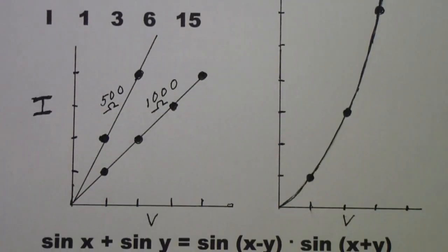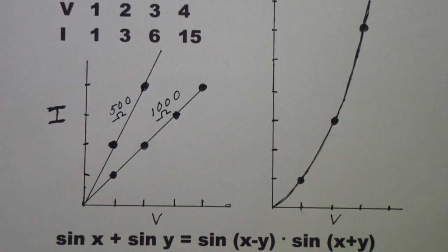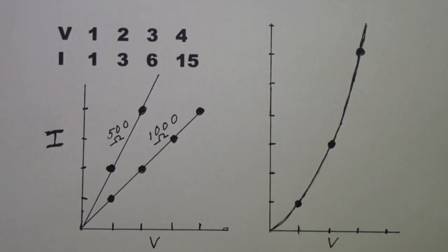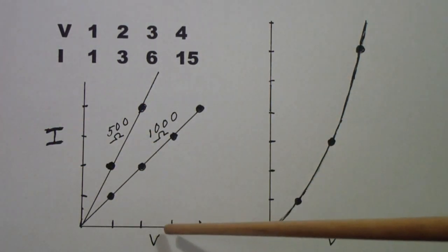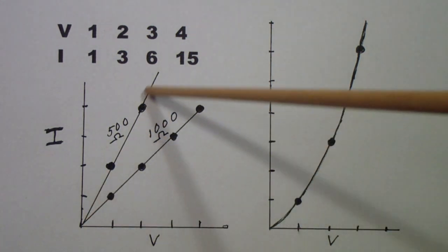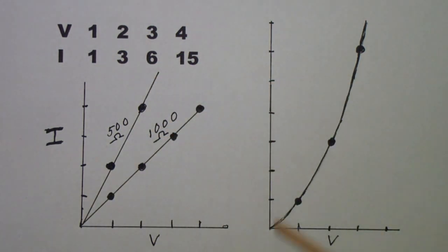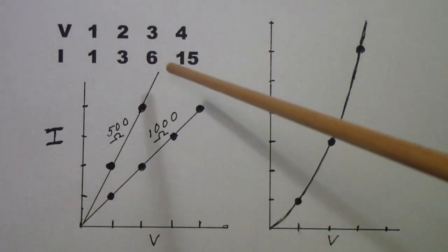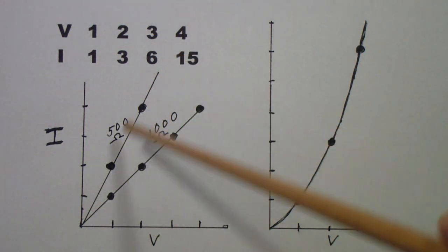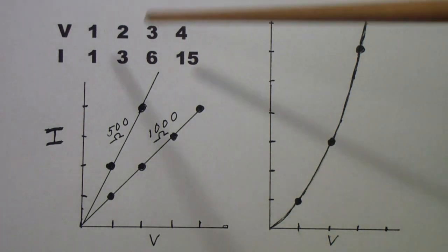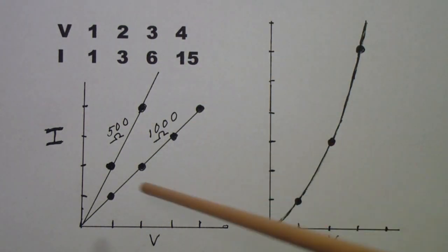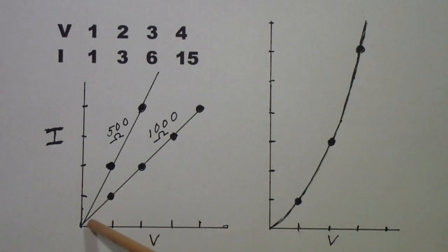So now let's look at what that means in terms of the curves. On the left, you see an IV characteristic for a 500 ohm resistor and a 1000 ohm resistor. Notice they are straight lines, and the only difference between them is the so-called slope. So a 500 ohm resistor has a higher slope than a 1000 ohm resistor because the current goes up faster, but nonetheless they are very linear. In other words, you can simply project this out as far as you want.